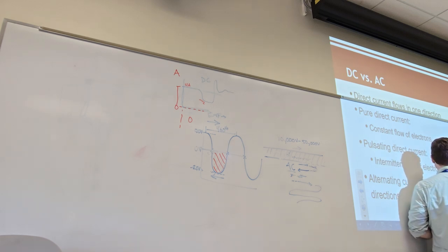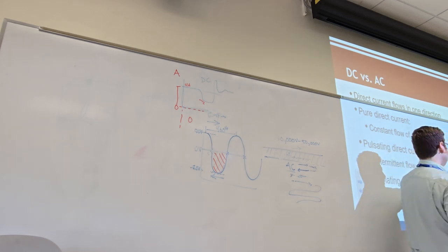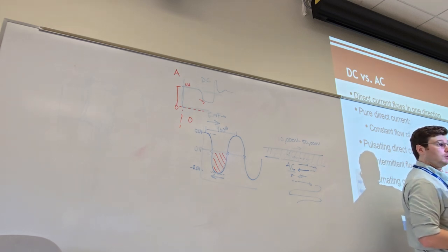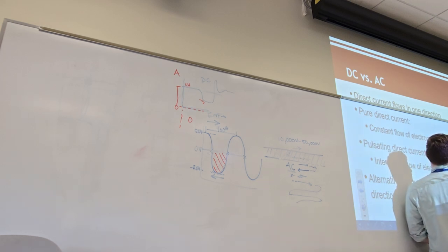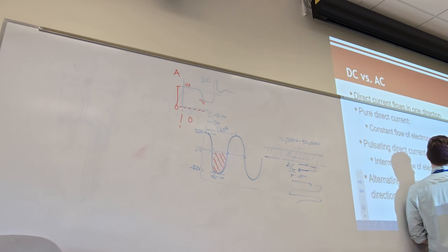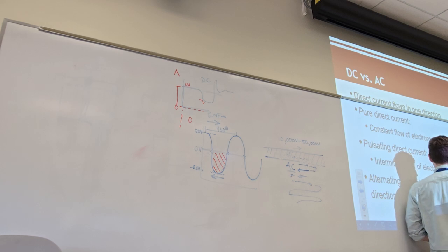The difference between AC coupled and DC coupled comes up all the time. This is on your oscilloscopes, on your power supplies, on your multimeter. This is an AC coupled signal. We only look at the AC component, the change over time, or sorry, the change without the DC offset. It's like we removed the junk that it's floating on top of, and we're only looking at the changing signal. That is our AC coupled signal.